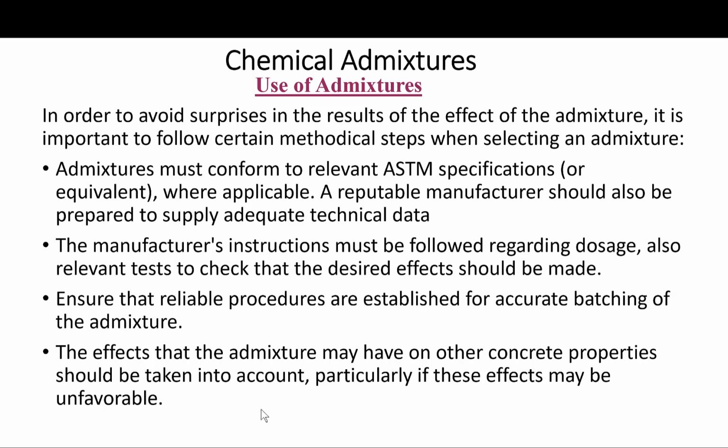Number 4, the effects that the admixture may have on other concrete properties. Again, we said they have side effects. This should be taken into account, particularly if these effects may be unfavorable. And again, sometimes some good side effects can arise, but mostly side effects will be unfavorable.